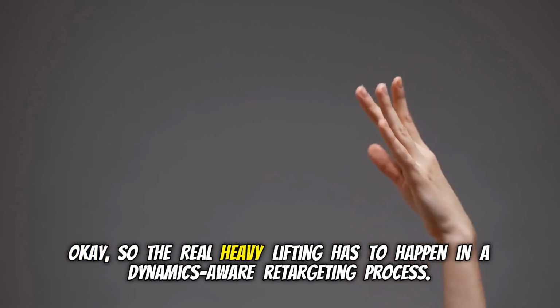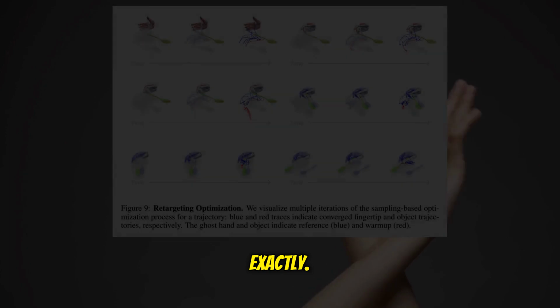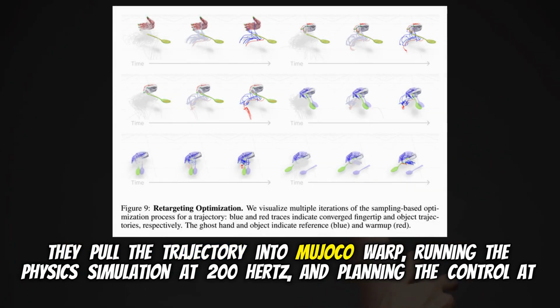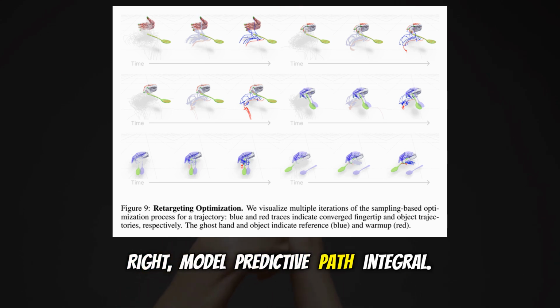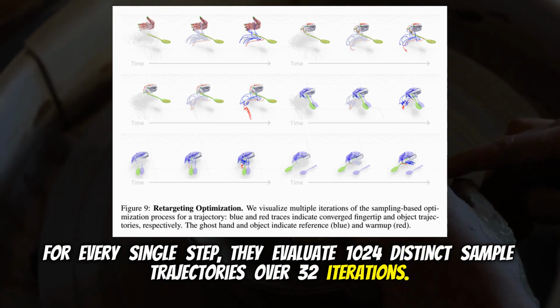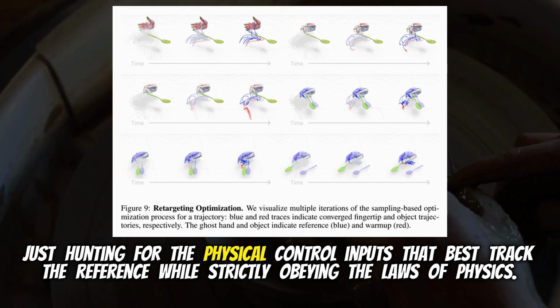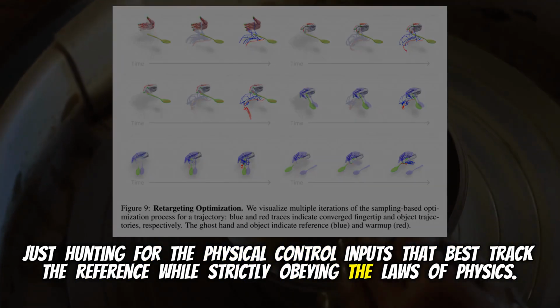Okay, so the real heavy lifting has to happen in a dynamics-aware retargeting process. Exactly. They pull the trajectory into MuJoCo Warp, running the physics simulation at 200 hertz and planning the control at 2 hertz. And they utilize an MPPI-style sampling-based optimization. Right, model predictive path integral. For every single step, they evaluate 124 distinct sample trajectories over 32 iterations, just hunting for the physical control inputs that best track the reference while strictly obeying the laws of physics.